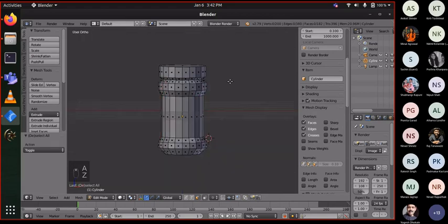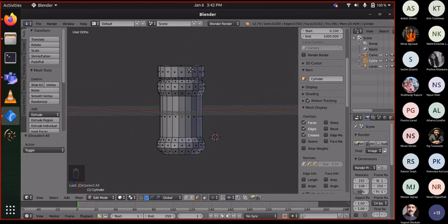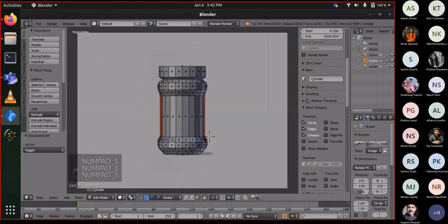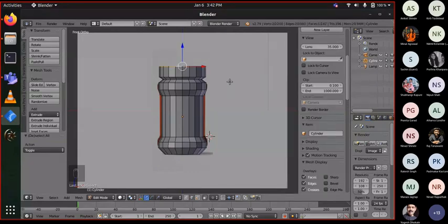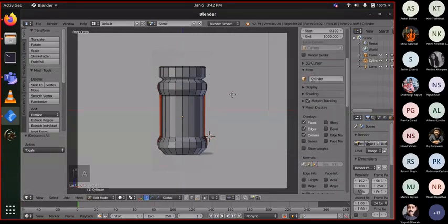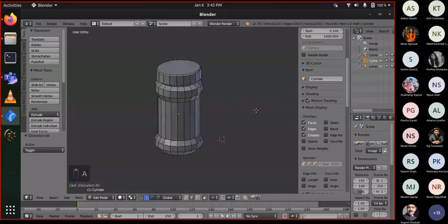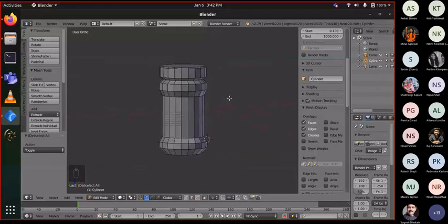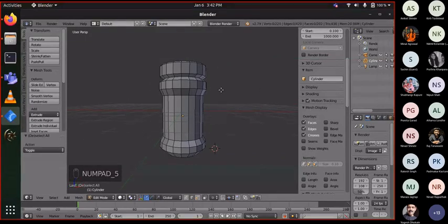And most of our object is pretty much done by now. For just one tiny detail I would like to add, we'll switch back again to the edge mode and add a little bit of bevel to the cap so that it is not as flat as it looks. So it gives a nice round finished shape over here. So coming out of the orthographic view, we can see our basic object is ready, right?